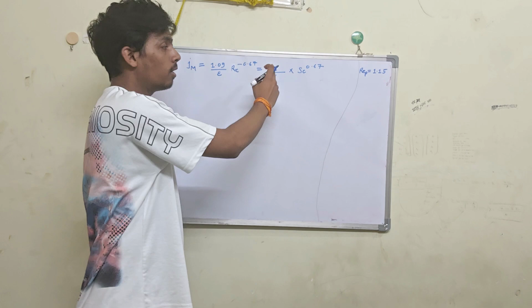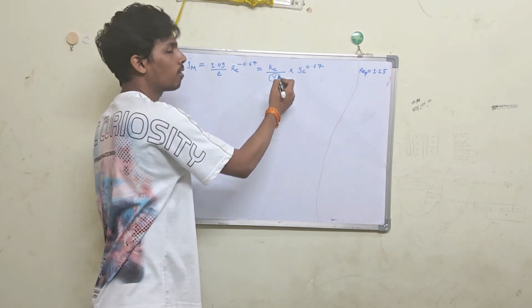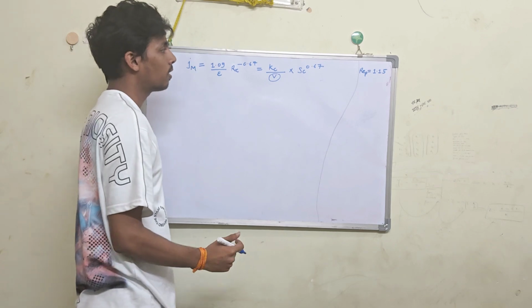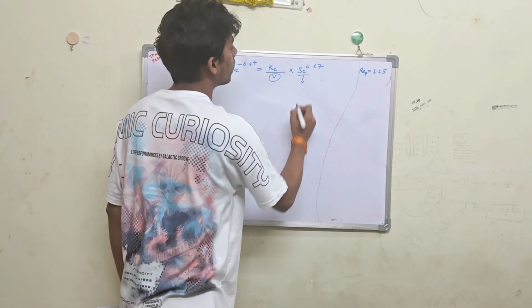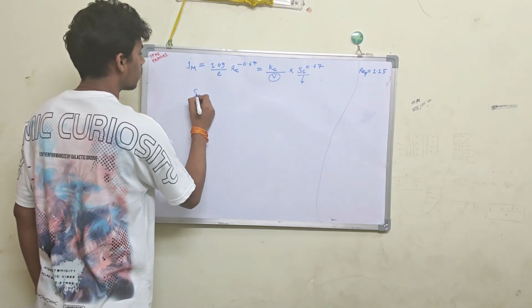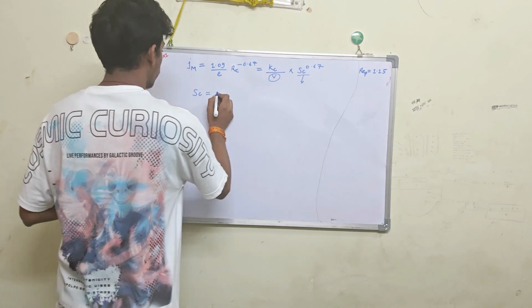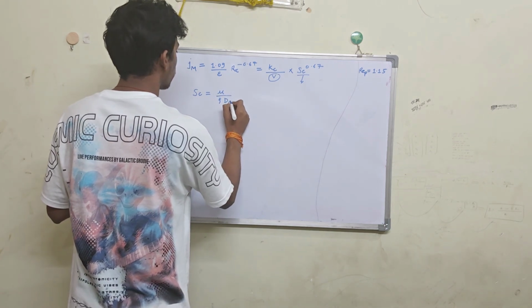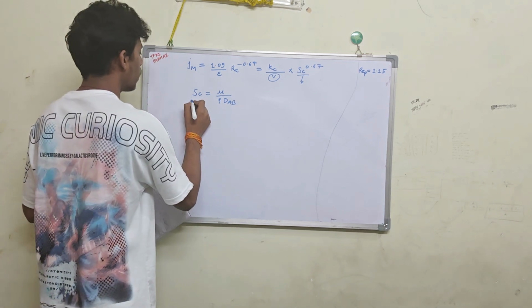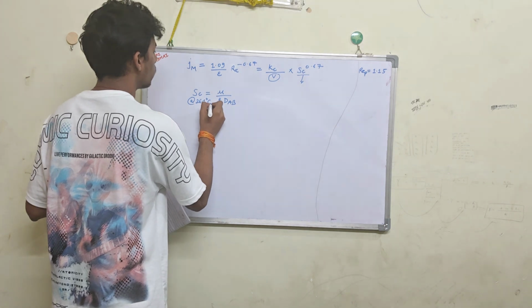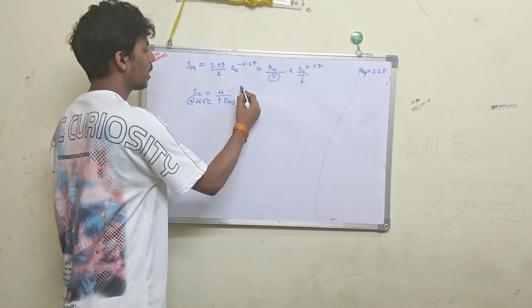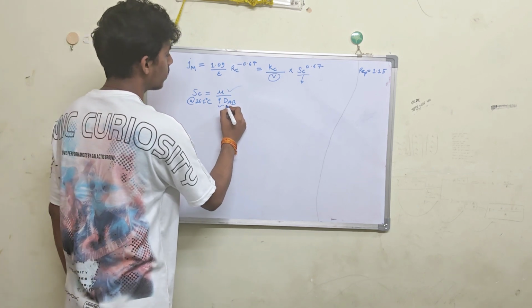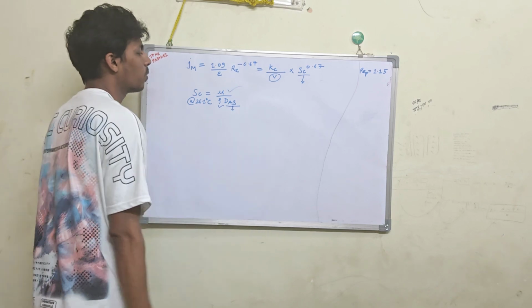Now this Kc we have to find, velocity we have calculated, volumetric flow rate divided by area, Reynolds number we have got 1.15. Epsilon value is given. The only thing which is unknown is Schmidt number. So the formula of Schmidt number you might remember is mu upon rho DAB. This Schmidt number we are finding at 26.1 degrees Celsius. Now this viscosity is given at 26.1 degrees Celsius. Density is also given. The only thing that we don't know is this DAB at 26.1 degrees Celsius.